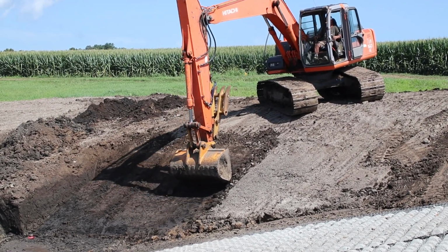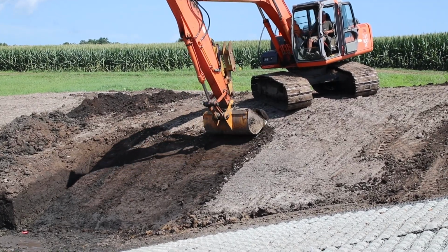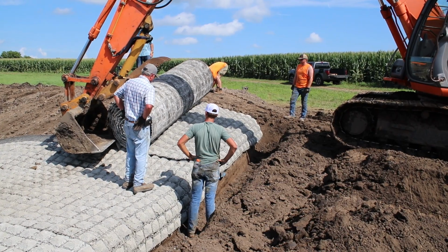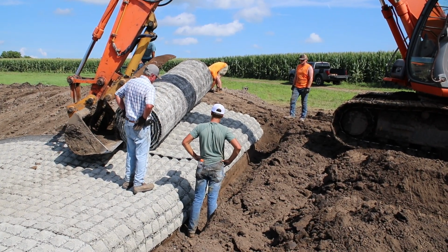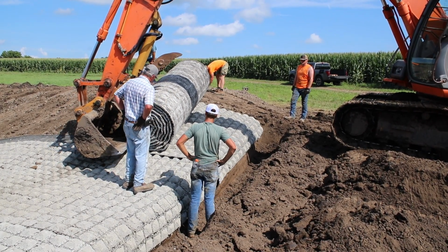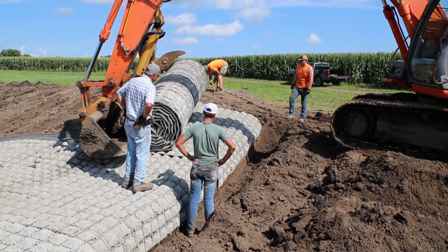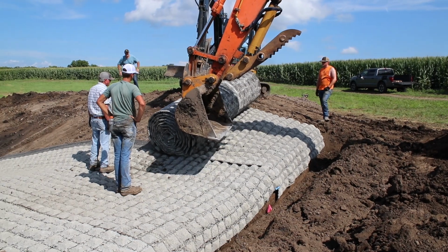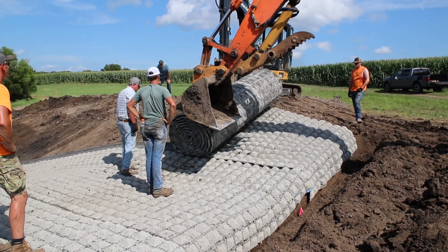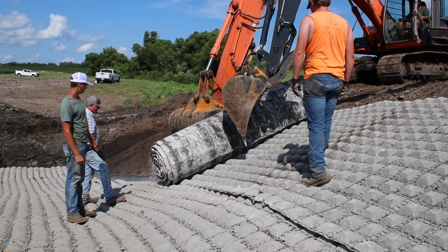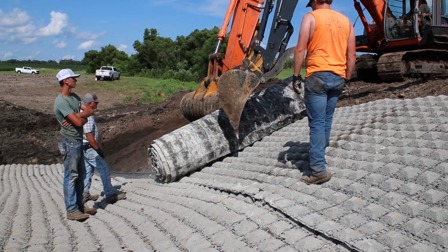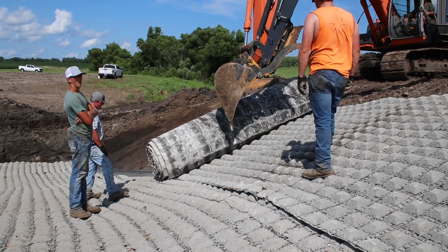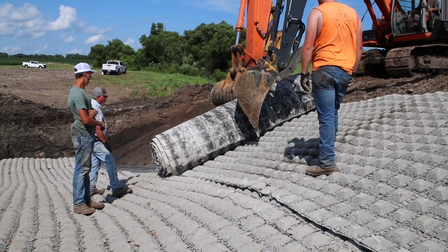Before they laid the final roll on the side slopes, they did some fine-tuning on the slope. Once they placed the roll, they discovered the roll was not close enough to the trench. The roll had to be nudged closer to make sure that 2 foot of the mat laid in the trench. When the mat is laid on the side slopes, it will eventually creep down slope as it is unrolled. On this last roll, the excavator and mini excavator worked together to unroll the mat down the side slope. Working together, the two excavators were able to better control how the mat unrolls and make adjustments as needed.